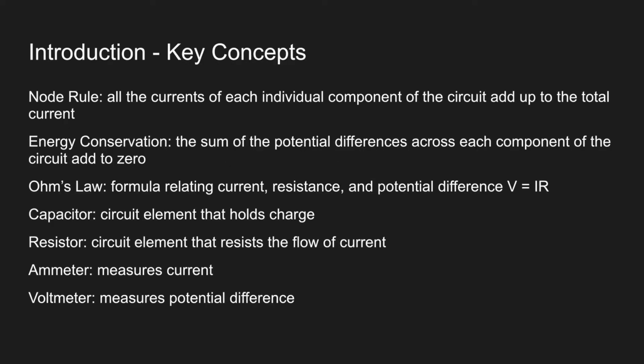The key concepts needed are the node rule, which states that all the currents of each individual component of the circuit add up to the total current, and energy conservation, that the sum of the potential differences across each component of the circuit adds to zero. We also need Ohm's law, which is a formula relating current, resistance, and potential difference,